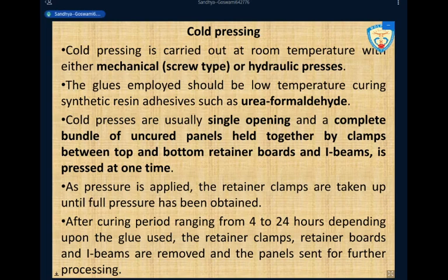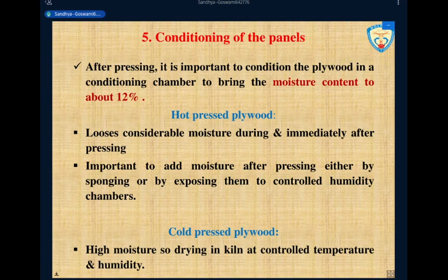So hot pressing and cold pressing, as we said, this particular slide gives you written material on cold pressing, and whatever I have explained is kept here. You can keep it as your study material. Fine. Thereafter, we will move to the last step of plywood manufacturing. Before the last step, in the sense, thereafter you will get only the trimming work, right?